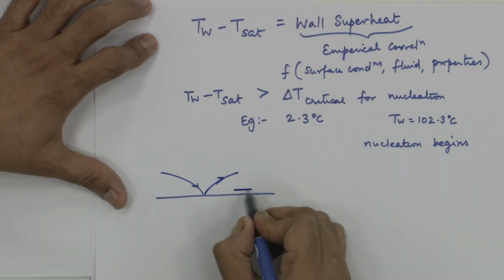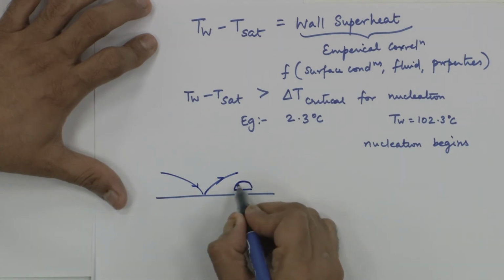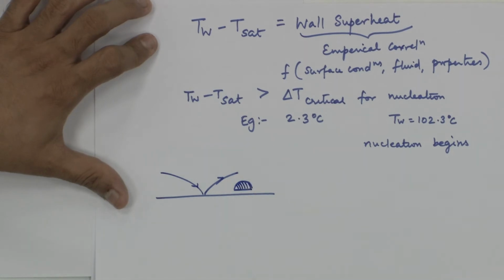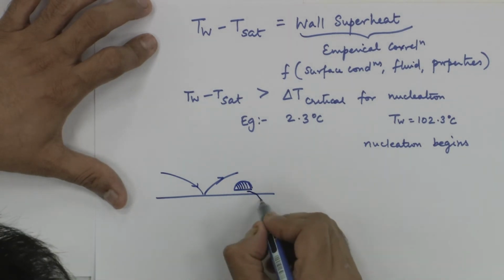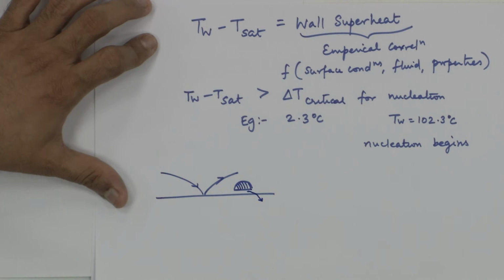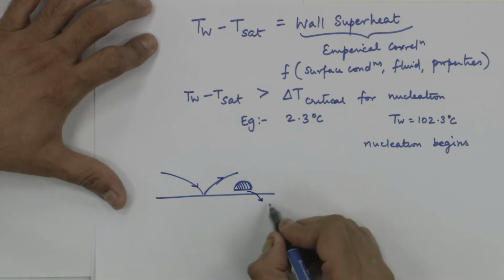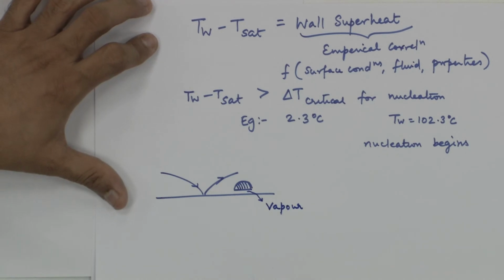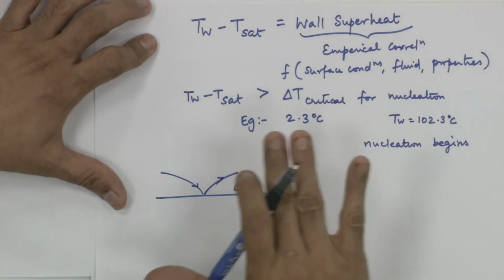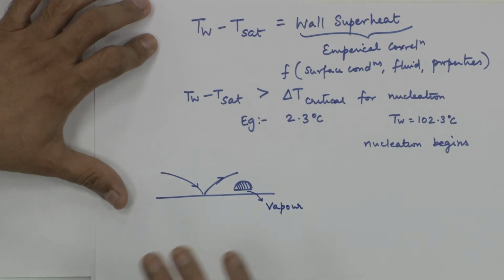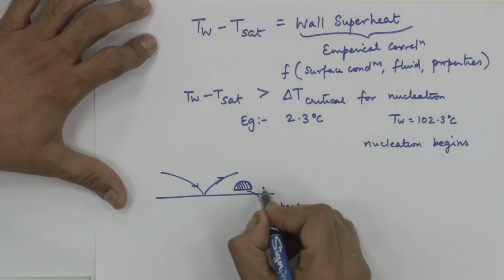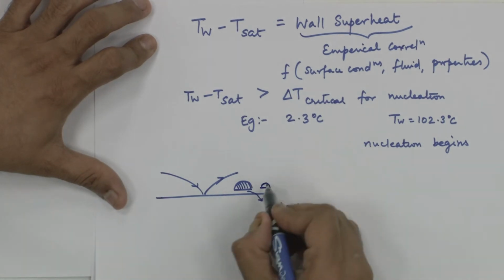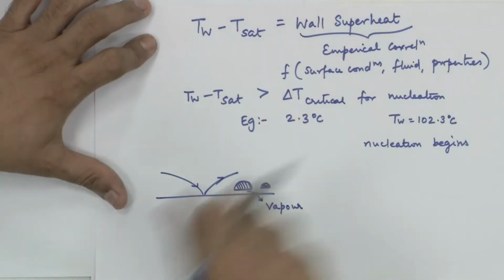And what will happen is this droplet would stay above the surface, because the moment the liquid comes in contact with the heated surface, vapor gets generated because of this very high temperature, and this vapor will form a cushion between the heated surface and the liquid droplets, and therefore you would see these droplets dancing all over the surface.